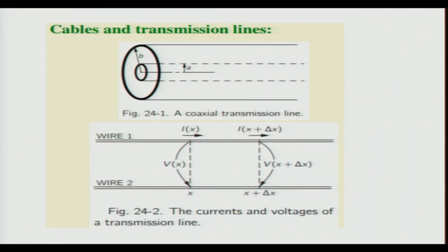So, because of this we will have to try to understand this whole device, this transmission line and cables, especially when the lengths are large, by a more complicated model consisting of both inductances and capacitances. At even higher frequencies, which we normally do not encounter in electrical supply systems, we may have to consider more complicated fields which cannot be represented by simple capacitors and inductors. We are not going to discuss this in detail, but I just want you to remember these